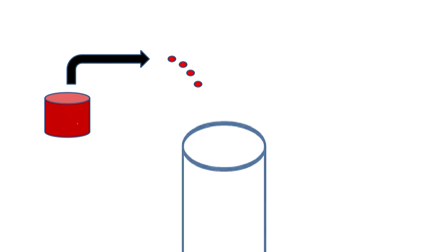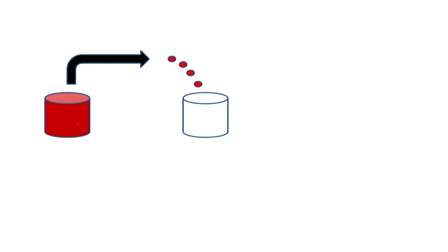Then you gradually add this polymer solution droplet, which is in chloroform, to a water solution, and this water contains surfactant. So, what will happen now? I have a chloroform phase and I have a water phase. So, basically I have an oil phase and a water phase. Oil and water will not mix with each other. This oil phase contains the polymer chain. Once you put this oil phase in this water phase, they will make a colloidal dispersion.